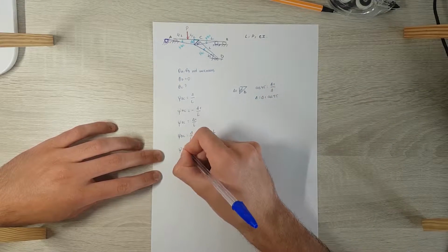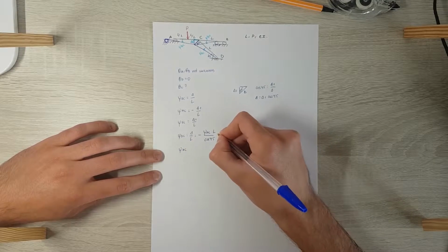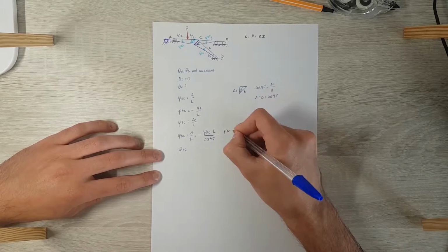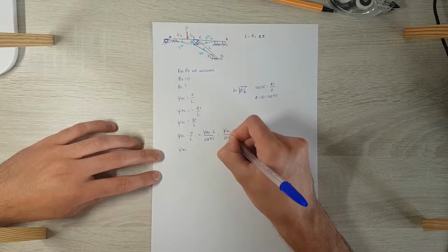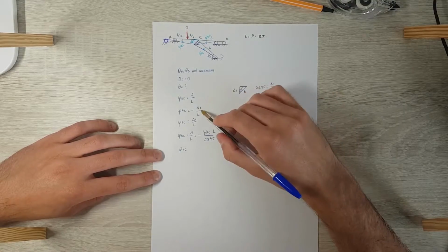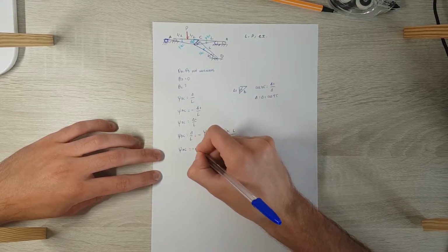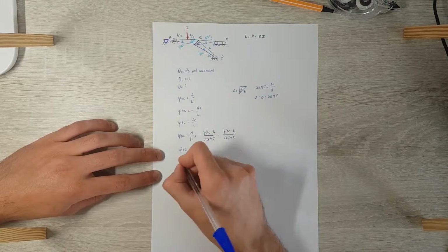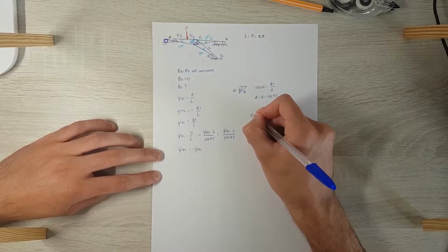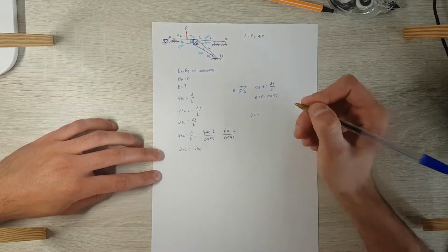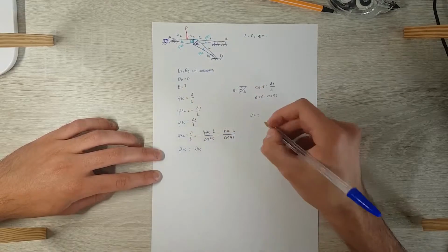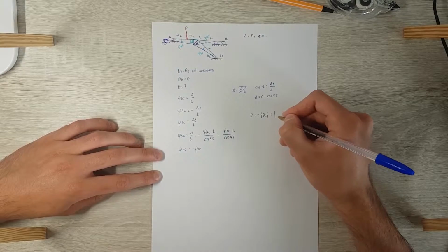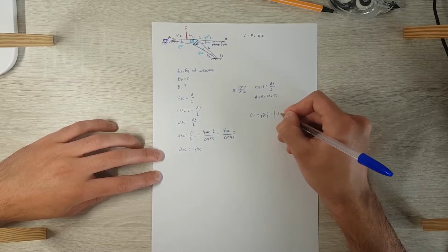And CAC is the same as CBC multiplied by L divided by the cosine of 45, because they are the same but with the opposite sign. So we have now that the degrees of freedom of the structure are this theta C and the CBC.